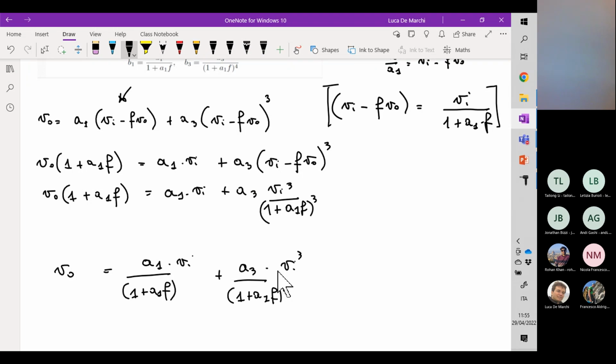So if this part here of the plot is basically our T of j omega, and this is the new 0 dB value, then to find the phase margin, once again, it is 180 degrees plus the phase corresponding to the omega 0 dB angular frequency.